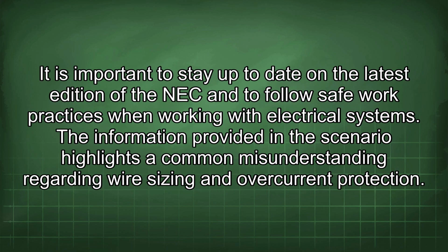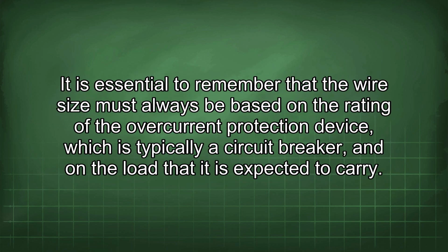It is important to stay up to date on the latest edition of the NEC and to follow safe work practices when working with electrical systems. The information provided in the scenario highlights a common misunderstanding regarding wire sizing and overcurrent protection. It is essential to remember that the wire size must always be based on the rating of the overcurrent protection device, which is typically a circuit breaker, and on the load that it is expected to carry.